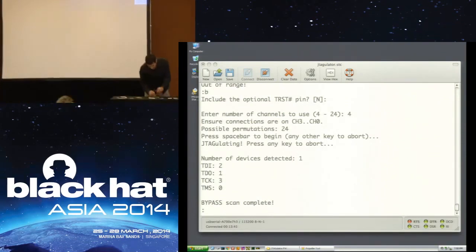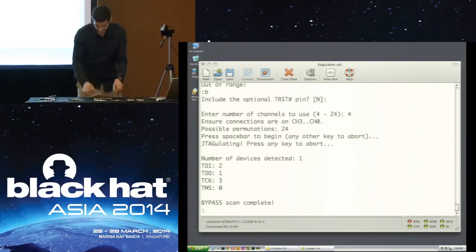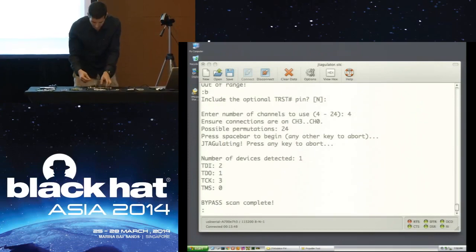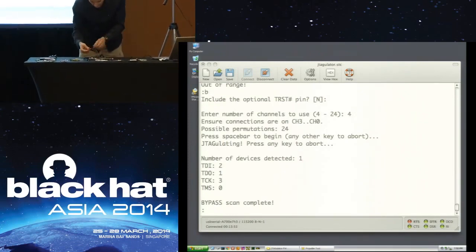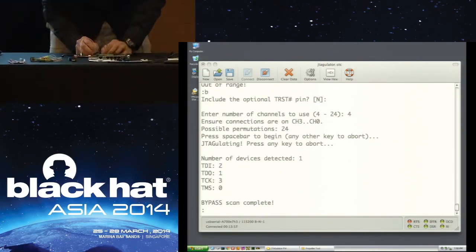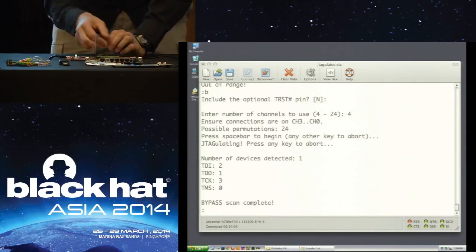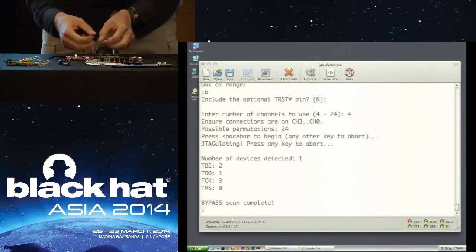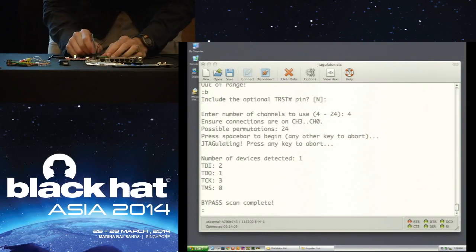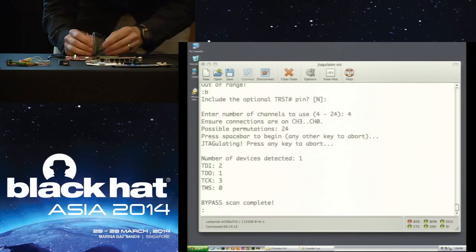All I'm doing here, you don't really need to see this on the screen. I'm disconnecting the JTAG cables, and I have a bunch connected to the UART, which now I know is the UART, but I don't remember what the pins are, so I'm just going to connect these up. It's a 2x5 row header, and looking at one side, there's 5 pins. I have ground hooked up, and then 4 other pins, so I'm going to connect those to CH0, 1, 2, and 3, just like I did before. And I don't care how they go in.